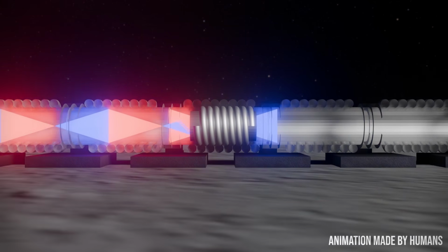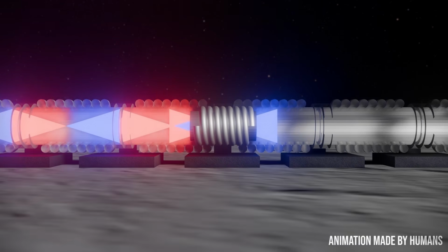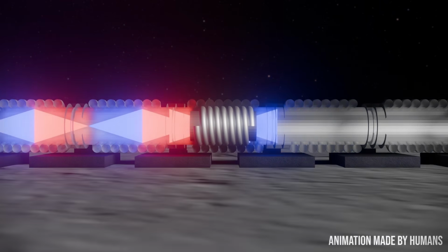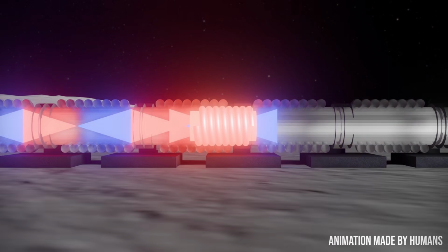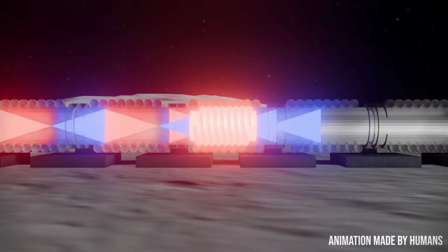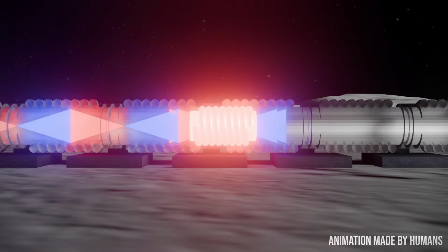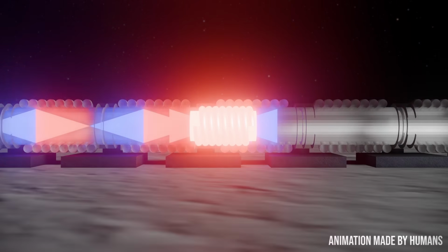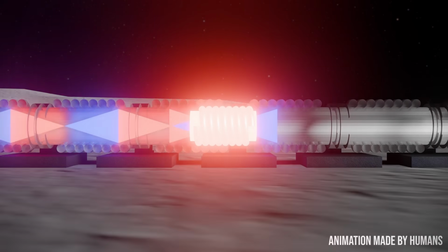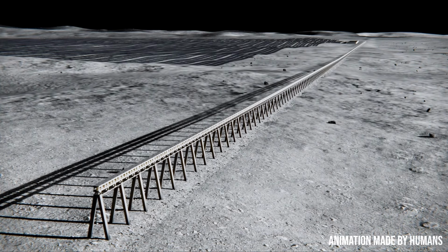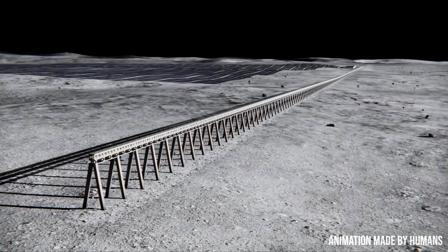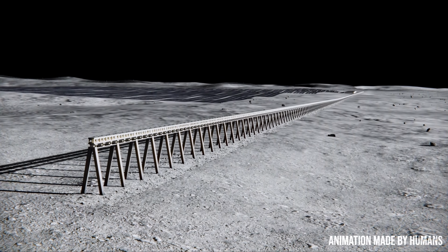For you see, a mass driver is really sized around thermal control. The rail segments or coils have to be large enough to not melt at any given current. That's what we mean by our hardware has to survive a certain amount of power, and thus how power dictates the size and why it's a governing constraint. Too much power just simply melts these things. So the consequence of power is thermal, and cooling with relation to power is what determines the size of the mass driver, the amount of tons of material it is made of.